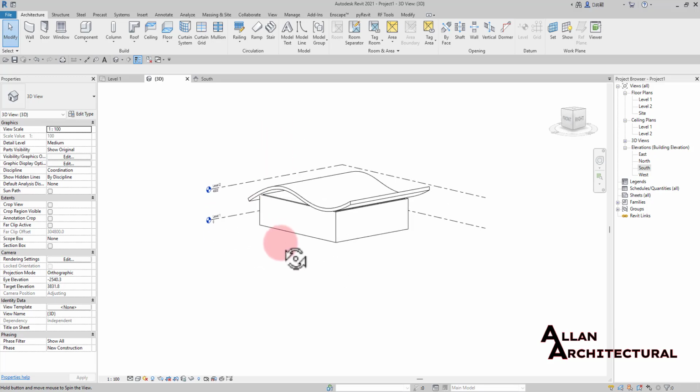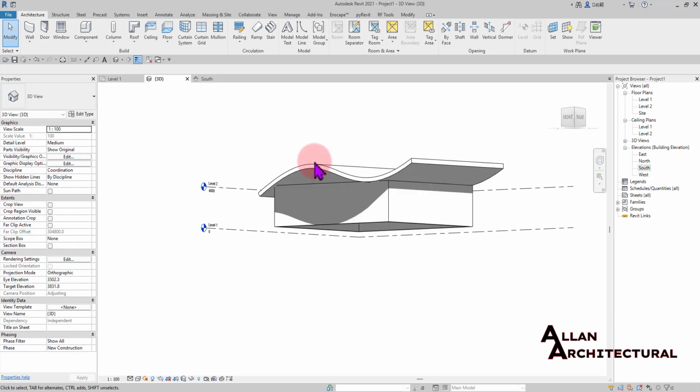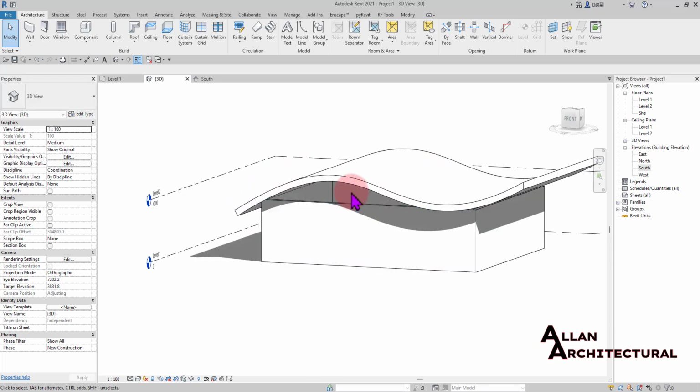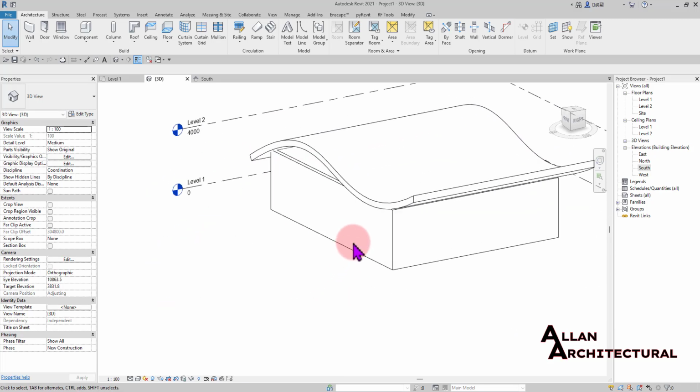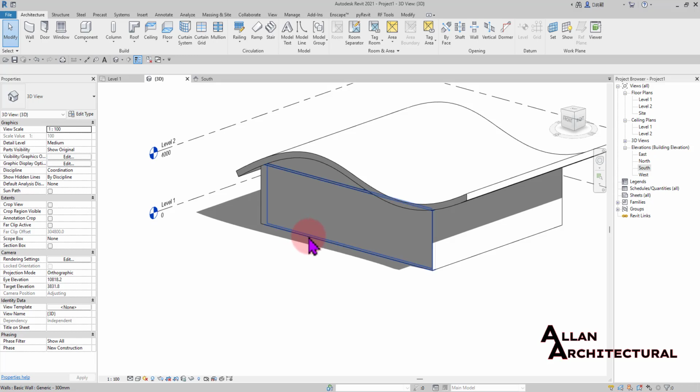So we can finish this roof in there, and what we can also do is we do not like that space in between our roof in there. So what we can do is we can just hover your mouse pointer right on any of the walls in there. I'm going to select this wall. So don't click on it, just put your mouse pointer on that wall in there, and then just hit your tab key once, and then it selects that roof.